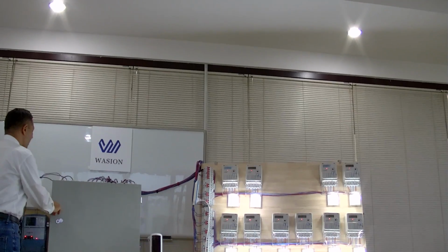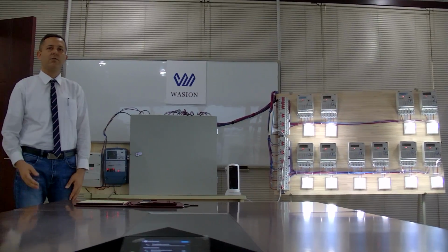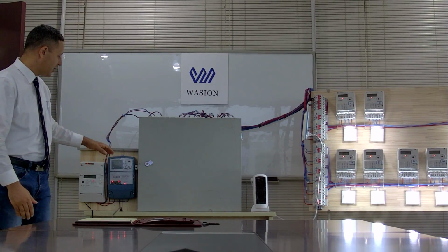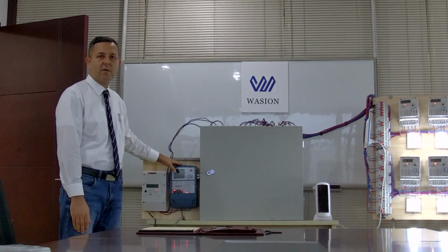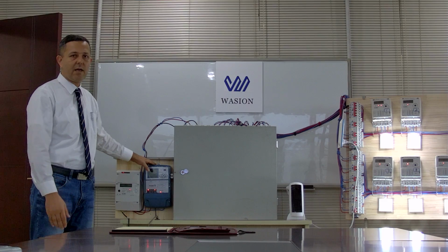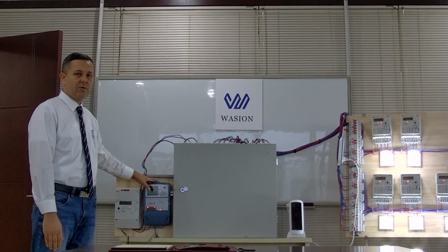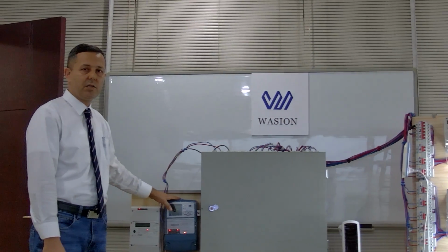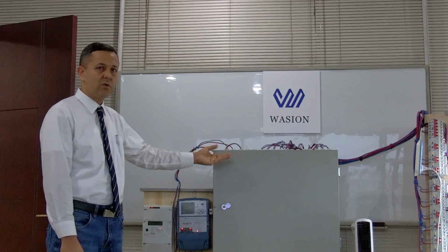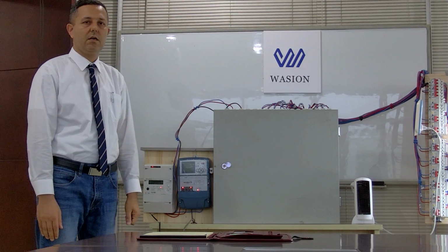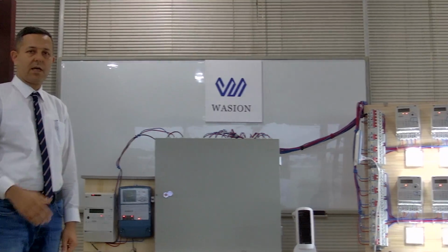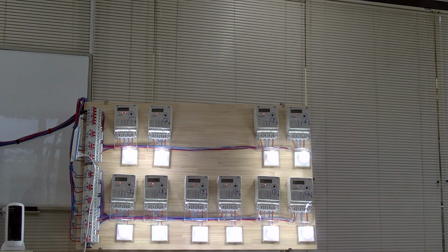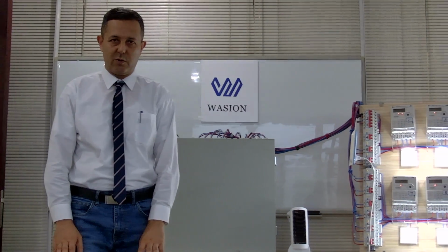So this is the command path. The commands are transferred from the system software to the DCU by cellular technology: GPRS, 3G, 4G, NB-IoT, Cat-M, and then transferred by PLC G3 from the DCU to the meters, and the meters will act based on the command and then send feedback again to the system software, and the system software will find out whether the command was executed successfully or not.